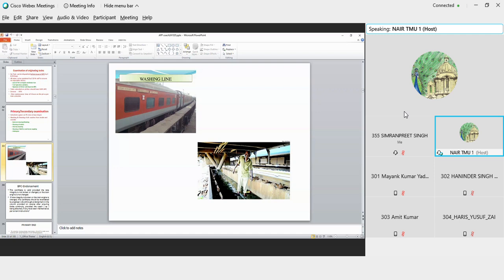And a minimum pit occupation time of 6 hours is required to do this examination. So you will have 2 gangs. One gang will start from one side of the rake, the second gang will start from the other side of the rake.